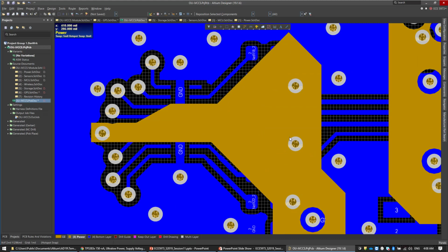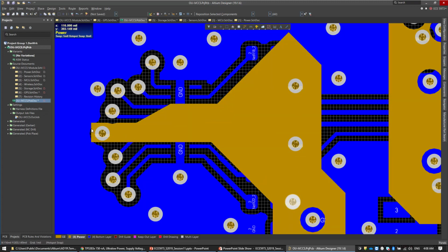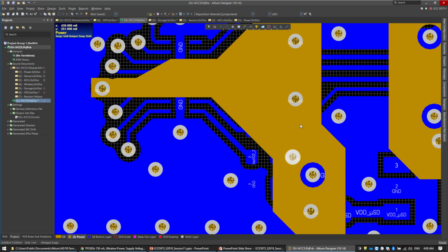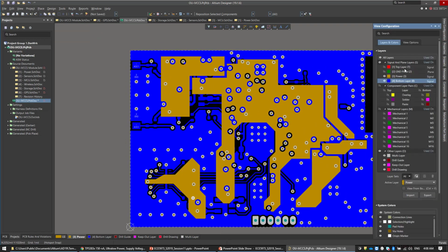layer or specific layer. So here again, look at the micro SD card in here. So I have a branch in here, you see, it's a branch in here. I don't have to connect this one with this one. No, they should not be connected together. Just branch them here, again here, you can see that here. And then on the bottom layer, how nice it is, everything is connected together. This is how you should branch everything.